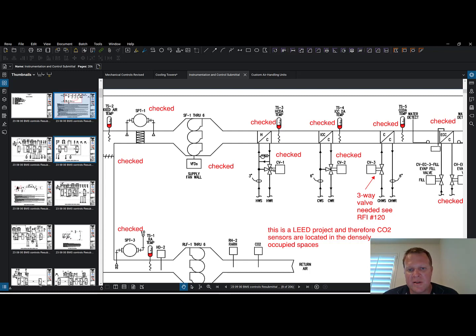And I'm assuming this is the valve, a control valve, would be my guess for CV. So it's got a control valve saying, hey, open or close based off of, are we going to try and heat this air or not? So we've got a control valve being controlled. What do we have here? That's a sensor. That's an input back to the controller.